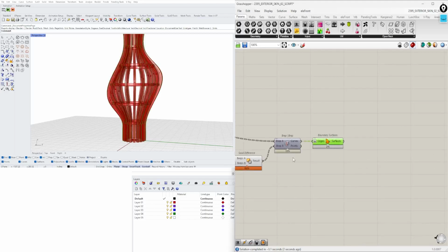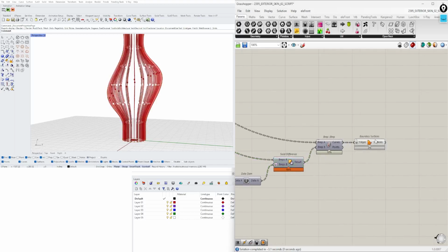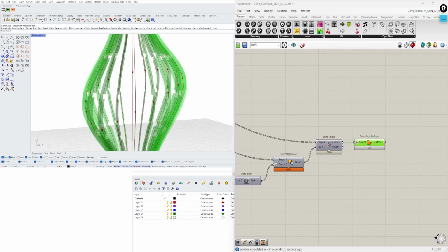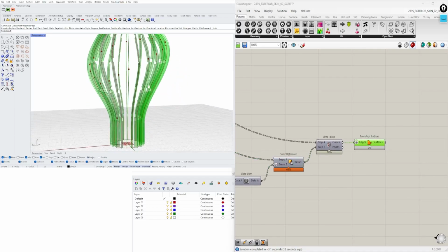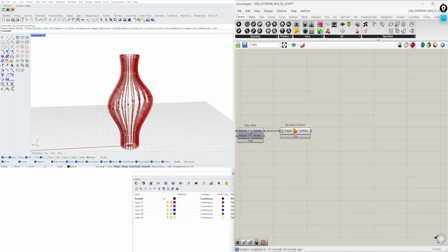And when we extracted these surfaces, now we need to take these and put them on a sheet. So what we'll do is, if you don't already have OpenNest downloaded, it is free. Once you download it and install it, you'll have this tab in Grasshopper.